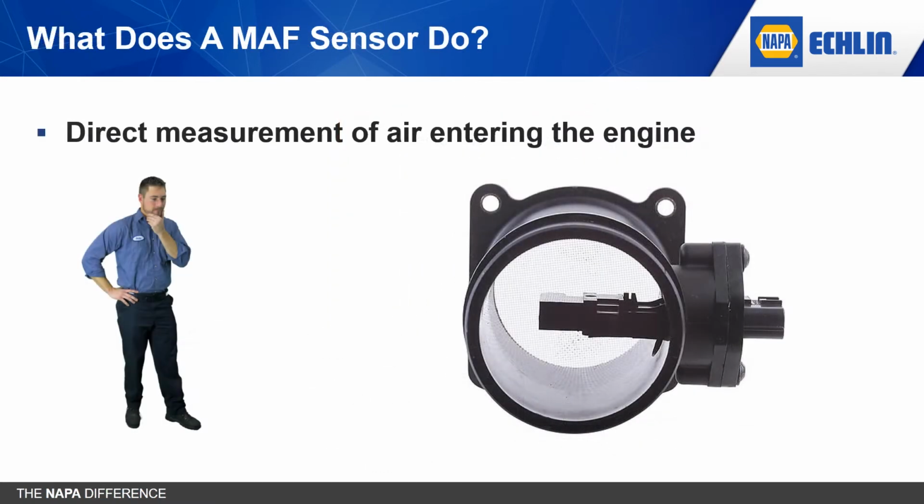So right about now you're probably asking, how does a mass airflow sensor measure mass directly? The sensor uses either hot wires or hot film element. The sensor's internal circuits will heat the element to a specific temperature. As air flows past the element, it will cool, and the sensor will have to increase the current to the element to maintain a specific temperature.